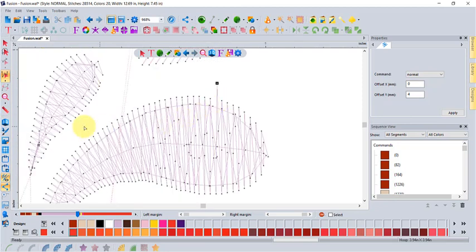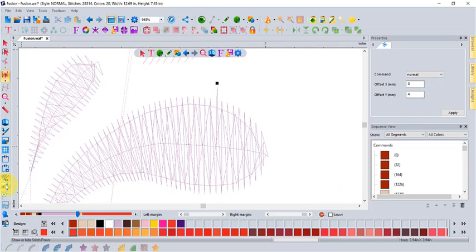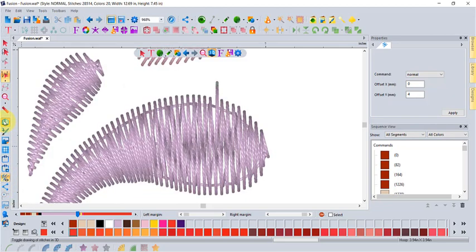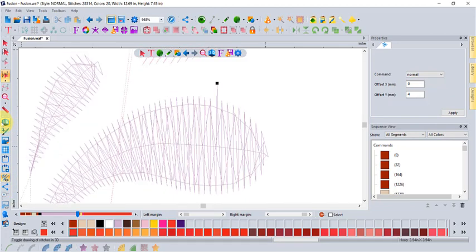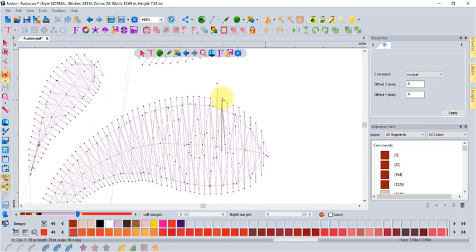So notice when I turn off 3D and turn off stitch points, I have more computer generated thinner lines. 3D makes the lines thicker. If you turn off 3D and then turn on stitch points, you can really see the stitches, and it makes it easy to select a stitch and make some kind of a small change to the way the design sews.